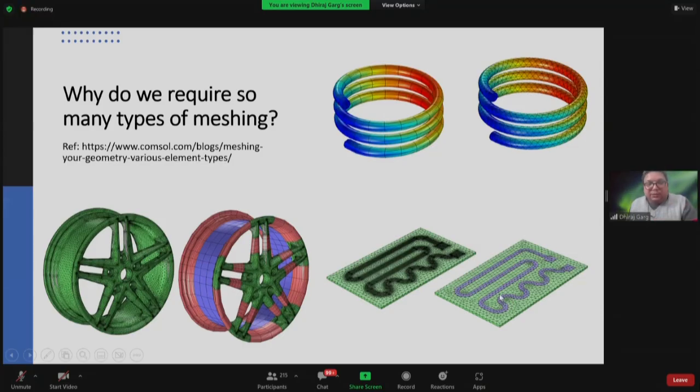Now if you want to couple it, let's say based on heat transfer the temperature inside the fluid is increasing. If you do not simulate the change in density and viscosity of the fluid along with the temperature rise or decrease, whatever the case may be, then you are basically decoupling the heat transfer from the momentum transfer, which may not give you a proper result. Or under some conditions it may be acceptable that the change in temperature may not have a significant impact. In such cases, you can use it and you may still get a reasonably correct answer.